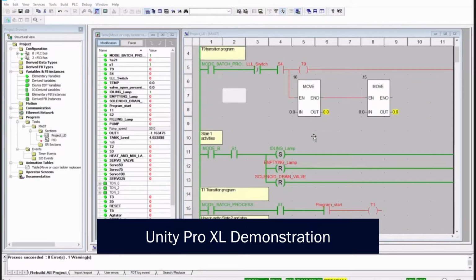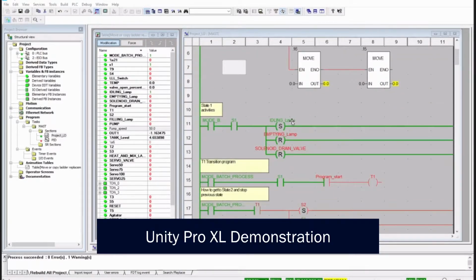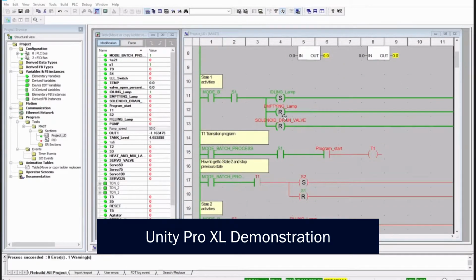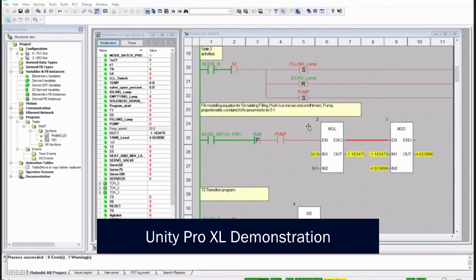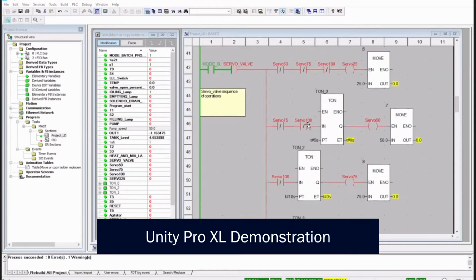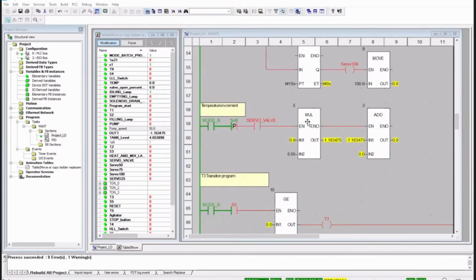In this case, we're using a ladder logic, but we can also use structured text or function block diagrams. Currently, we are in simulation mode. This basically just means that we can simulate the PLC under normal operating conditions, and we can use an animation table as seen on the left to check whether everything is working correctly and that all the values are as they should be. Once we have built and uploaded the program to the PLC, we are able to view the system through CitectSCADA.